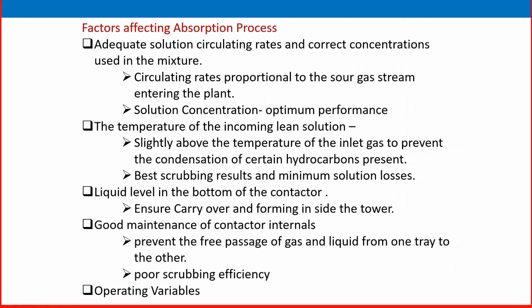And moreover, operating variables in the absorber are pressure and temperature, circulation rate and gas flow rate, and contamination concentration level. All variables are very important. In the stripper, temperature and pressure are very important, as well as purity and internals maintenance.